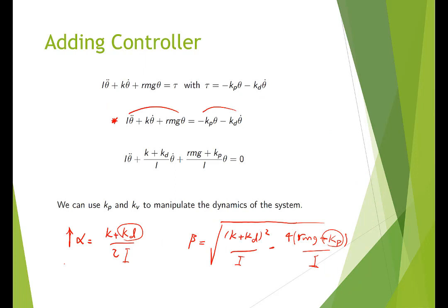Also, when we add the proportional, the spring term, Kp affects the oscillation term as well. For instance, increasing the Kp would make the oscillations worse, increases the complex part. Reducing it makes the oscillation smaller. So you can see that when we add a spring and damper, it can help to change the solution of the equations.